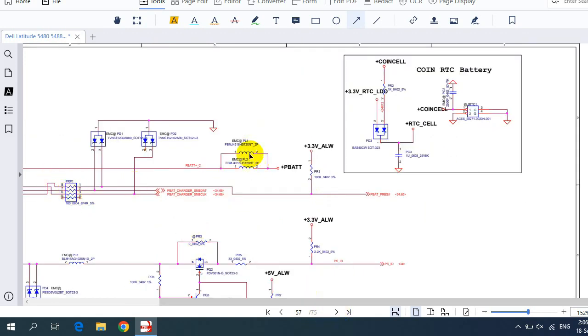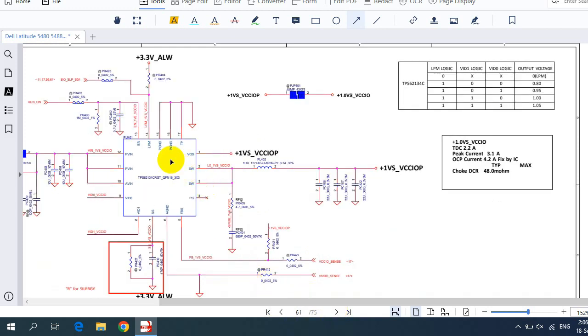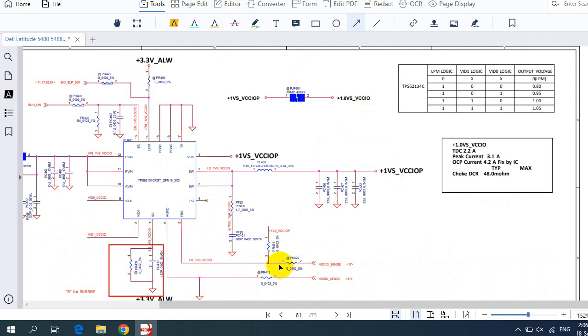So network resistor, inductors, resistors, MOSFET, double diode. This is basically a basic circuit that you can find in every laptop, without MOSFETs. Of course, we have the IC here. We don't have MOSFETs over here because the power is just 1 or below 1, or even 1.1 volt. The designers don't use the MOSFET. Okay, so we have just the IC, the inductor and ceramic capacitors. They also don't use the chemical or electrolytic capacitor; it is missing here, but no problem.